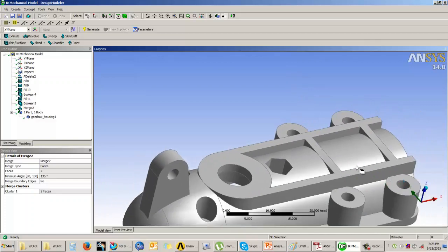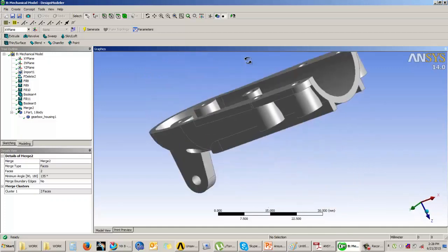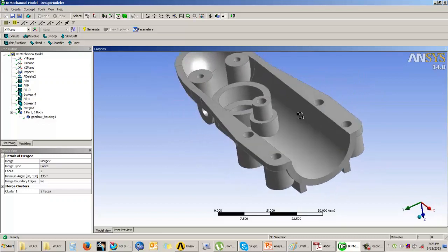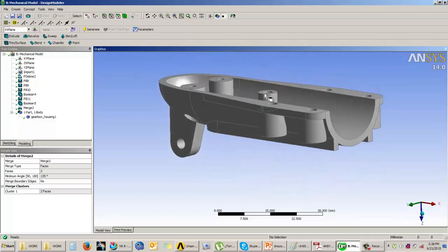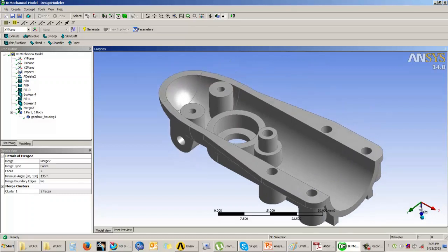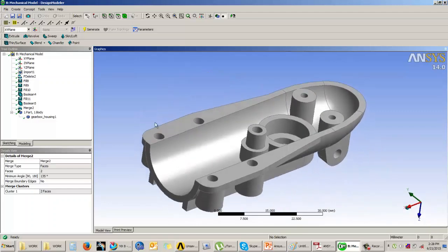Okay. So here you can understand that we have done some editing in the geometry. We have removed some features. We have filled some volumes, and we've also used the Boolean operation. Now, as we discussed that the geometry is symmetrical about the ZX plane, instead of considering the whole volume for analysis, we will only consider half of the geometry.